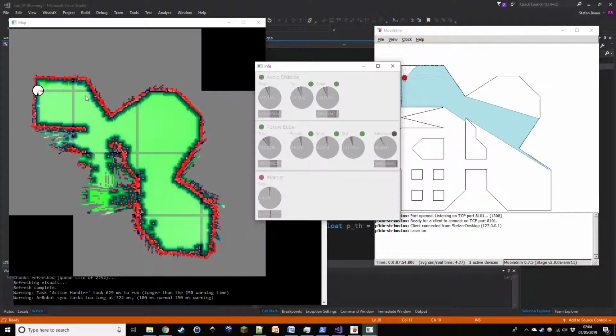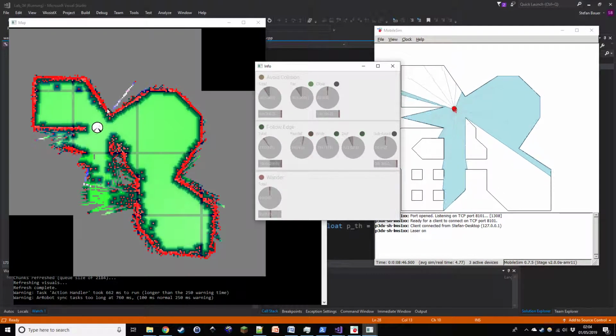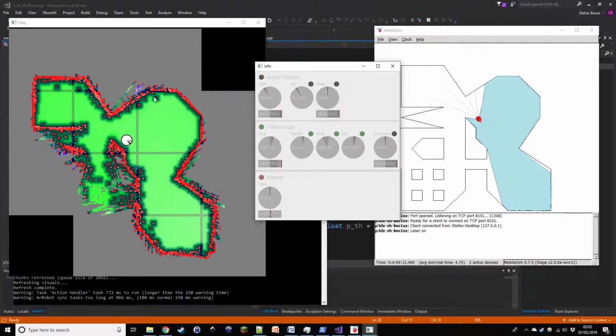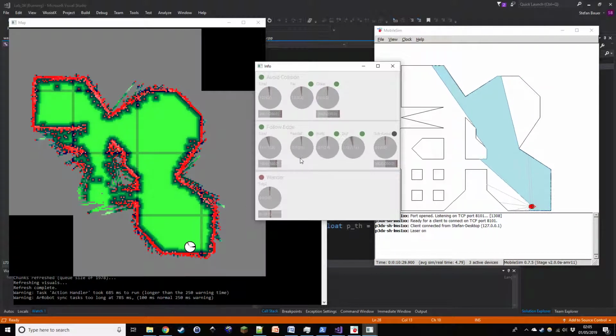The blue component of each pixel demonstrates that the robot is penalised for getting too close to walls. You'll note that, of course, the sonar is slightly imprecise, so it has a lot of these extra tiles that have been inaccurately described as being filled. You'll note that they are getting overwritten as being empty, so it has a certain amount of noise correction built in, which is good. You can see that the edge following is functioning fairly consistently.